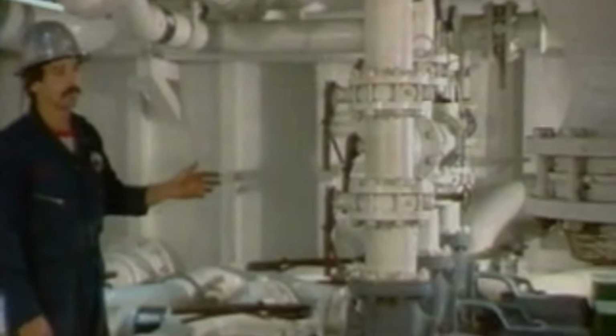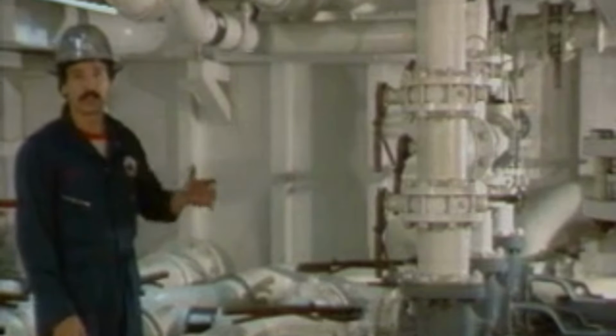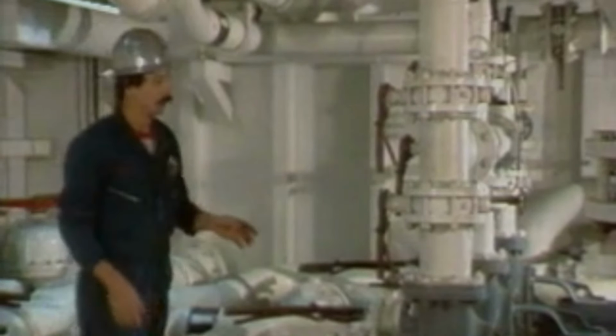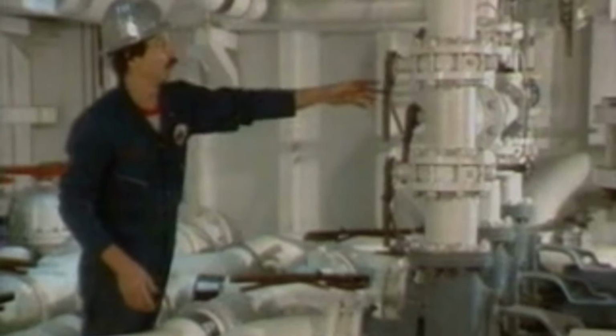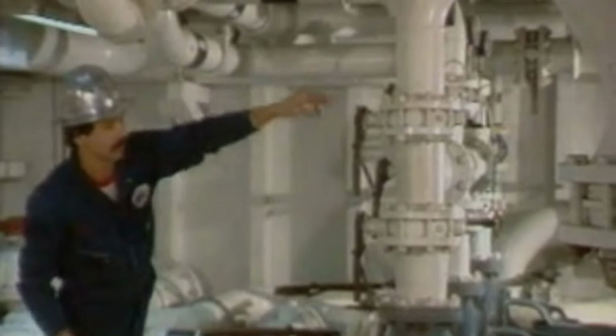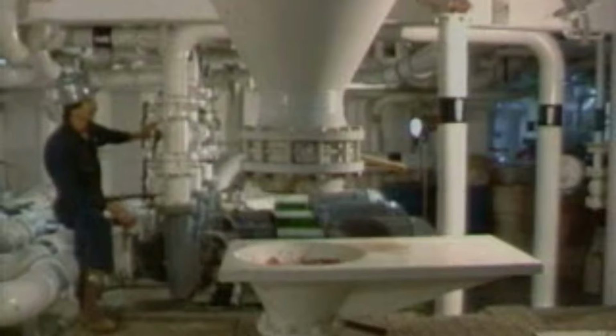This system enables you to transfer mud with any pump that you have to any pit, to various spots on the rig. The way I've got it lined up is after it's being drawn through the centrifugal, it'll be discharged through this line here, which is the line to my hopper system. You'll notice these valves here are open. This valve here is closed, which stops any discharge from going any further. It isolates it.